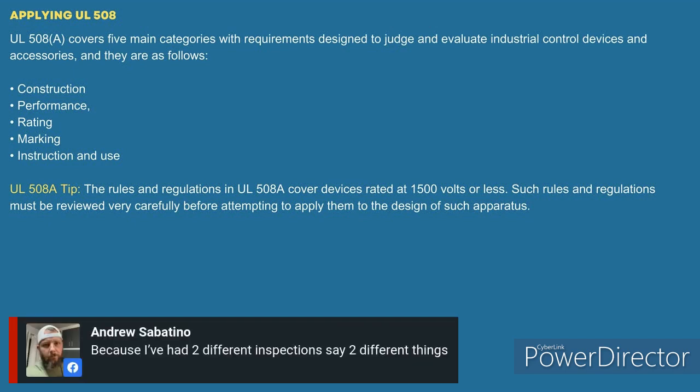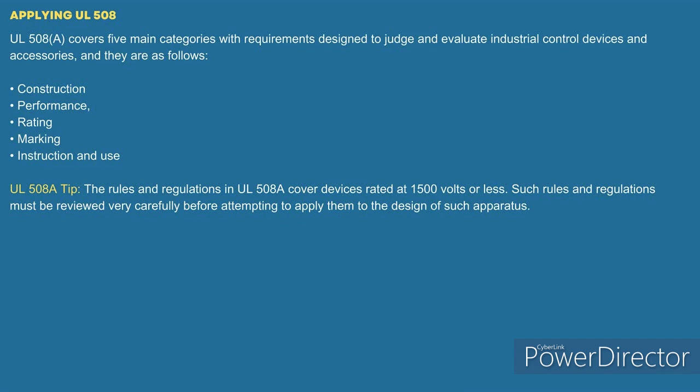So one thing I wanted to answer for Andrew, I agree with you, sir. There are so many different inspectors that interpret things different ways, and what I would say to the inspector is, is it likely to be worked on while energized? If the answer is yes, then yes, it needs clearance. If the answer is no, we can isolate it upstream and work on it in an electrically safe work condition, then no, the working clearance is not required.